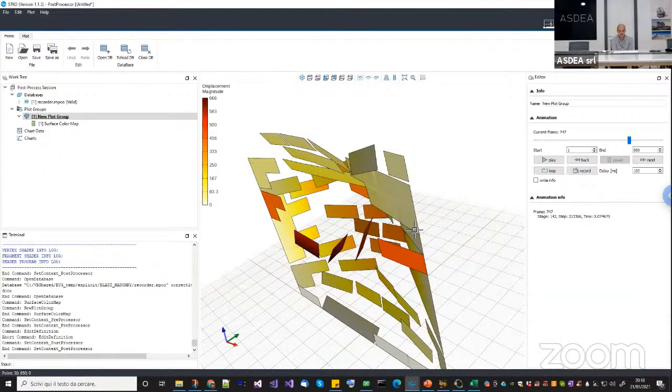Exactly. No, I understand what you're saying now. In that case, the accelerations are absolute, not because you removed the constraint, but because you did not apply an acceleration using a uniform excitation. You applied a force, and that force is causing an acceleration. So in that case, it is absolute. The only point in OpenSees where the accelerations are relative is when you apply the acceleration at the fixed degrees of freedom using a uniform excitation. Okay, that is the only one.